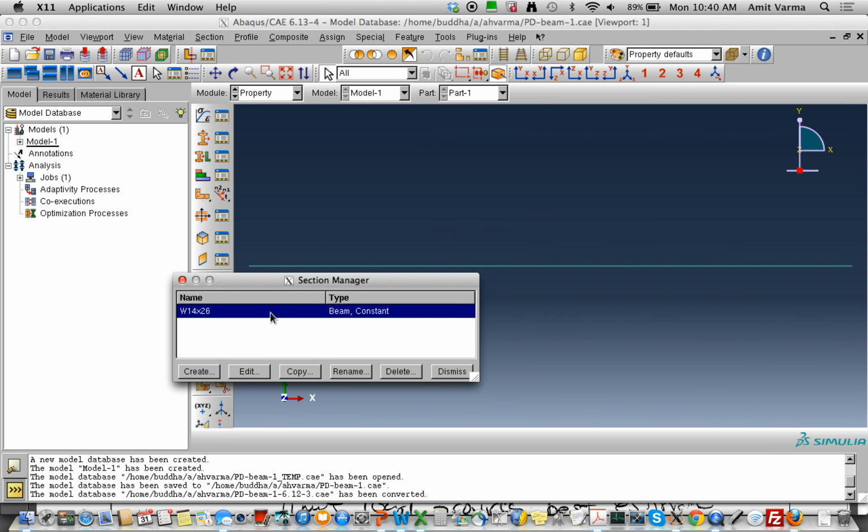When you select an I shape, it gives you all of these options to define what the cross-section looks like. And there's only one thing I need to explain to you, that's little l here. Do you see little l? Little l is this parameter right here, and that's the location of the centroid. So for the wide flange, it will be equal to half the depth. Should not be a problem. And the dimensions B2 and B1, as you can see, they can be different. T1 and T2, T3, all of those are thicknesses of the individual elements. So you'll just write in all of those numbers right here, and end up defining the cross-section.